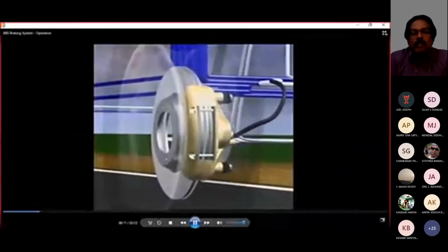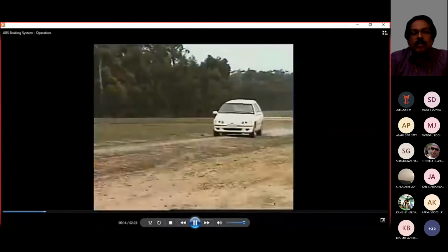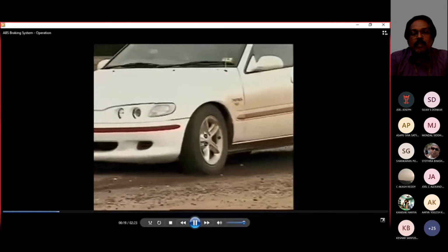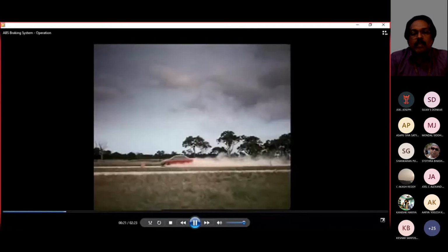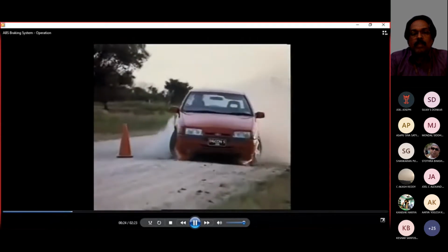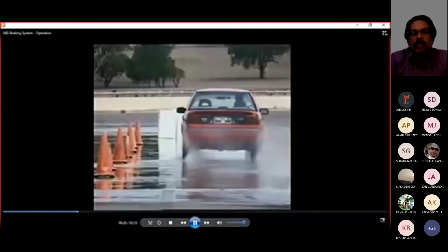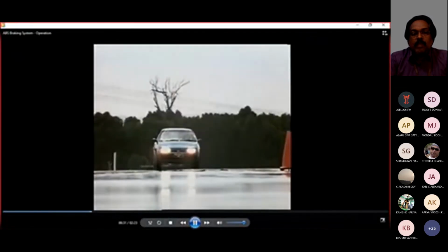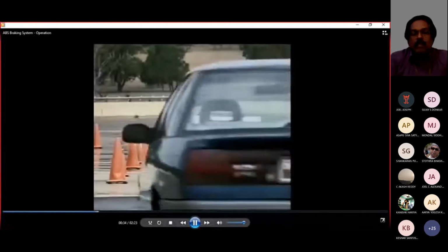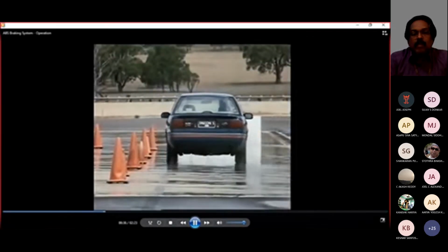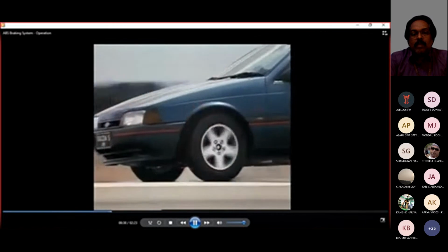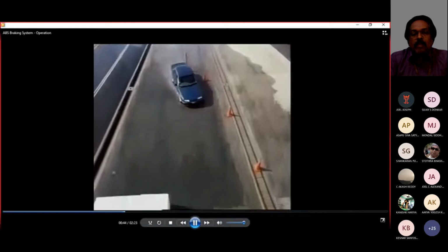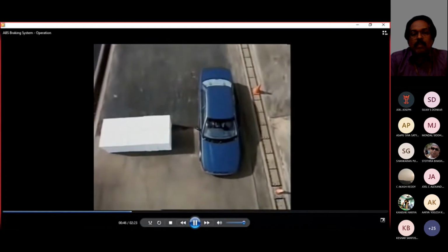This section examines the anti-lock braking system. Applying brakes too hard or on a slippery surface can cause the wheels to lock. When wheels lock, steering control is lost and, in most cases, it produces longer stopping distances. The anti-lock braking system prevents wheels locking or skidding no matter how hard brakes are applied or how slippery the road surface. Steering stays under control and stopping distances are generally reduced.